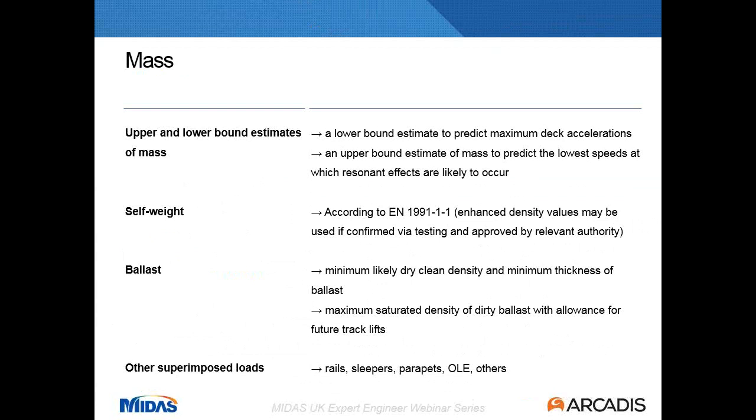You also have to make sure that you're considering masses for everything that goes on top of your bridge, and that's the rails, sleepers, parapets, overhead electrification, everything that will contribute to the dynamic behavior of your bridge.